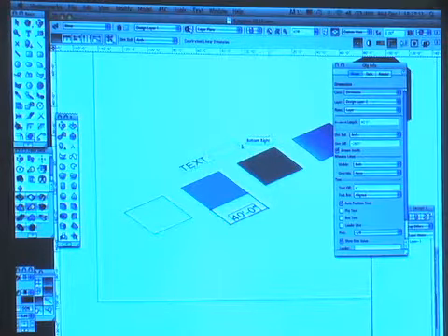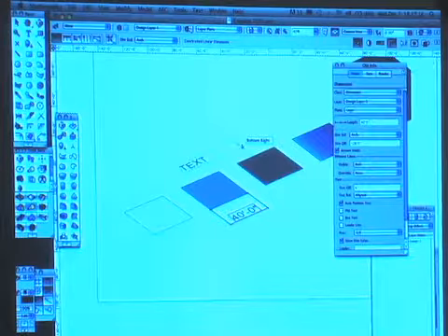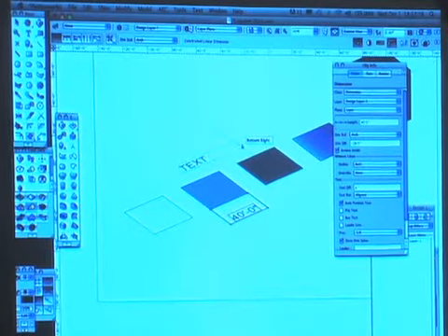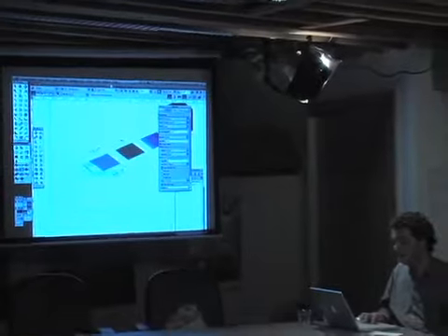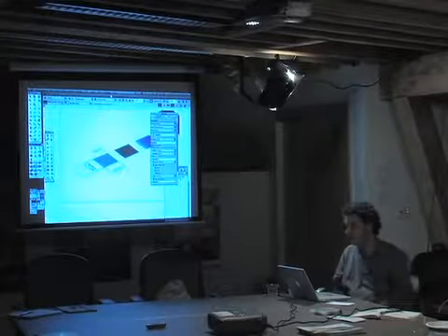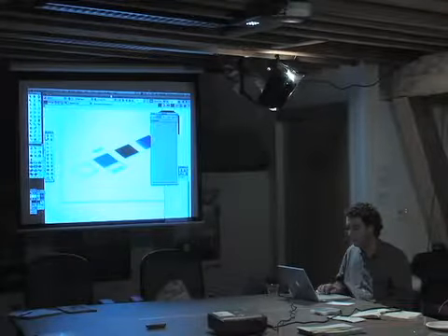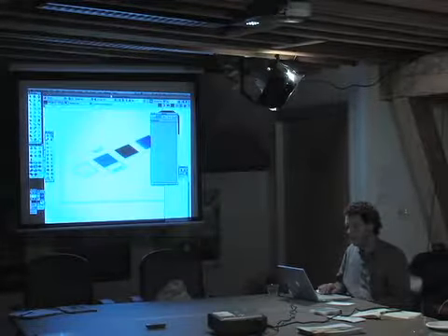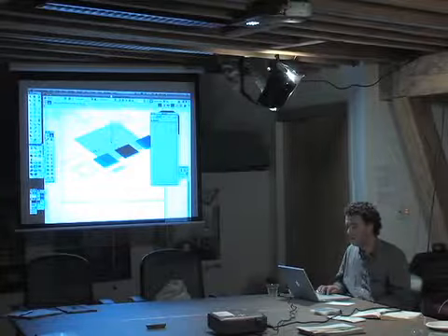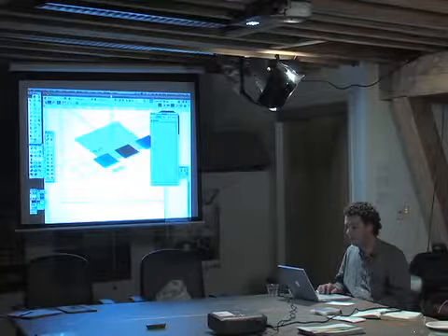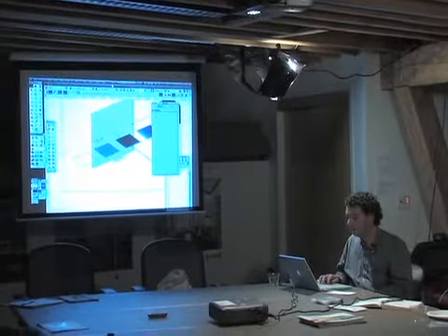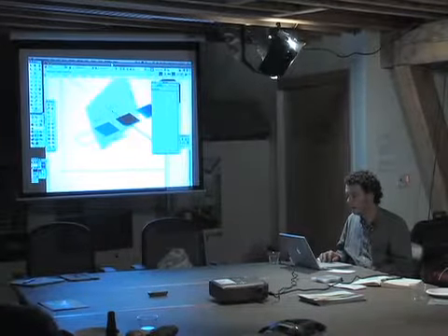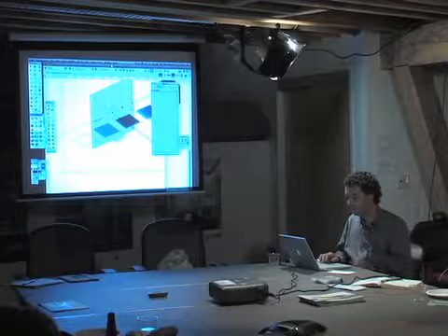So yeah. Now, before in 2010, it would allow the dimensions to rotate, but it would just have a box where the dimension should be. So now you're able to dimension in 3D as well. So working planes are important in this version, and they're easier to set up. If you click on this working plane, you now have these buttons to be able to rotate them around, spin them around, and reorient them pretty quickly on the fly.